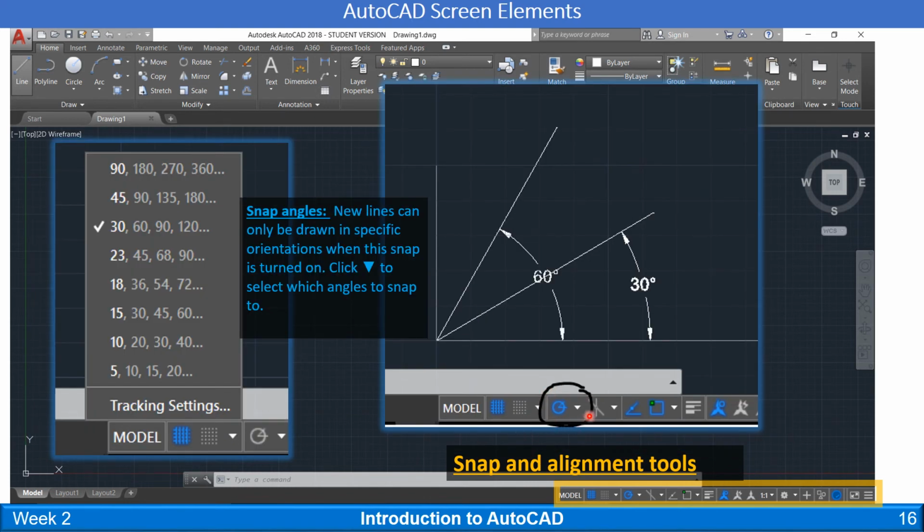Okay, next to the grid is this little guy, and this will align your angles if it's on. So if it's highlighted blue, when you draw a line at an angle, it'll snap it to be exactly 30 degrees or 60 degrees or 90 degrees. If you pull up this little menu at the side, you can choose which angles to have it snap to. So that can be a really nice tool.